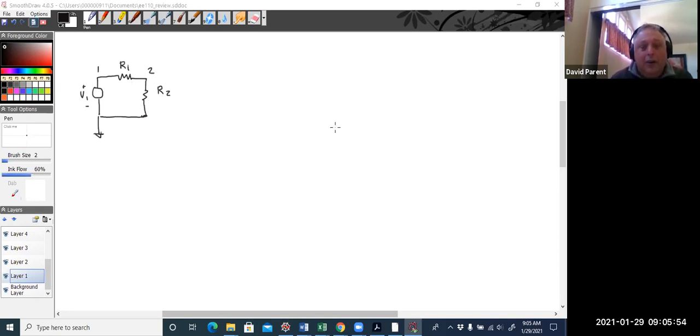And if you start writing equations, that might not be as helpful as saying, well, I notice this is a voltage divider circuit, and the larger R2 is compared to R1, this voltage will go up. If R1 is a lot larger than R2, then this voltage will go down. Okay, now let me write out the voltage division equation and solve for it, and then you've kind of explained your thought process. All right.